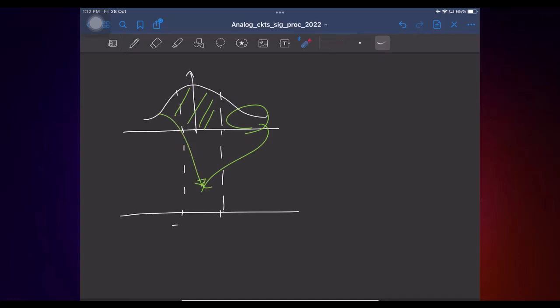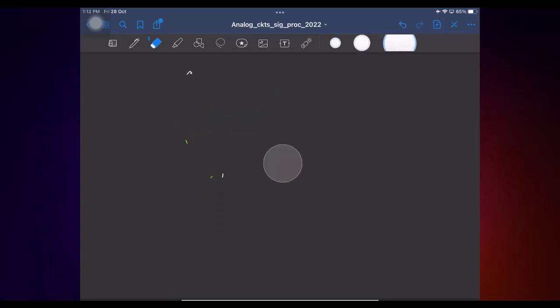So when you have to find the mean square noise, you will integrate this entire curve. That gives some value. Now we will integrate it over minus fs/2 to plus fs/2, and that is basically the same as integrating the entire curve. Does it make sense? Intuitively, we can say that the samples will follow the same pattern.